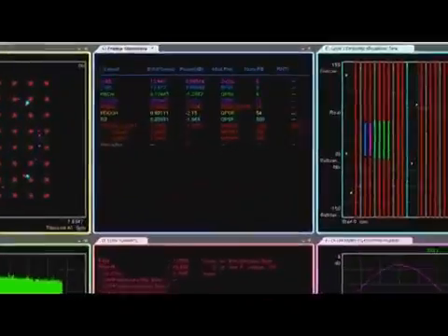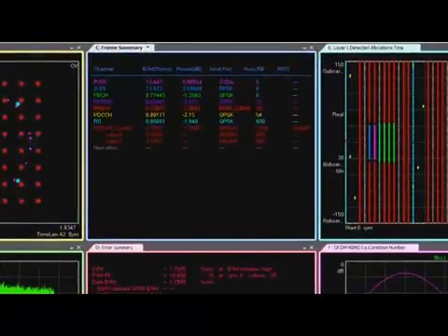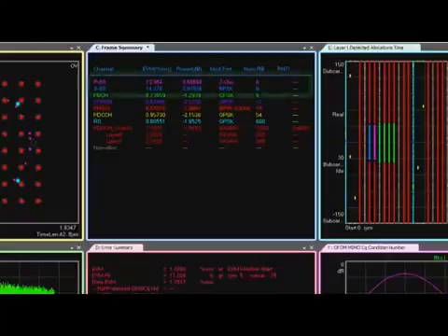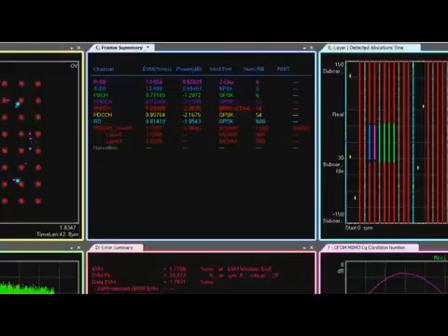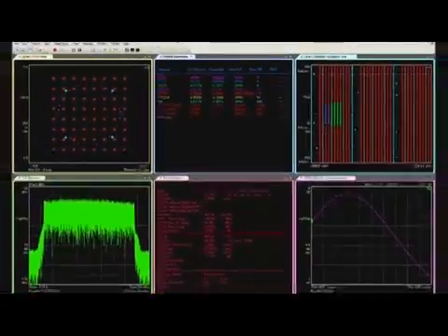The frame summary display shows EVM and power levels as a function of signal components such as the synchronization signals and various physical channels. For MIMO signals, analysis of the physical downlink shared channel, or PDSCH, is broken down by transmit layer. This analysis breakdown supplies valuable information when diagnosing and locating the source of problems in a transmitter.